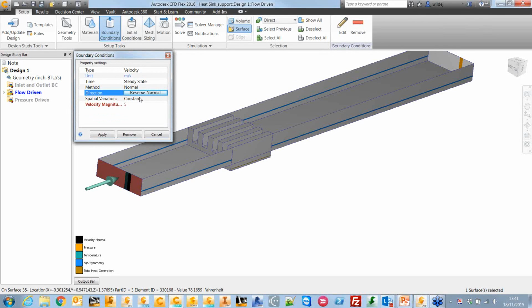And then the other is where we use mass flow rates and the total conditions. So when we assign, say, a temperature, instead of static, we could assign total, which would take into account the static and dynamic values. We only really use this for compressible models, and the same for the unknown condition. Quite frequently we might see models that are pretty simple like this, with flow rates at the inlets, temperatures at the inlets, and then an unknown at the outlet. We've got to remember that it isn't unknown, it's probably atmospheric conditions, so we should give CFD a pressure reference. So unknown conditions are really only used for compressible models.